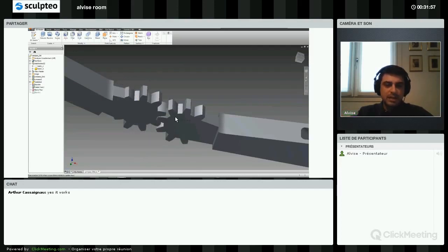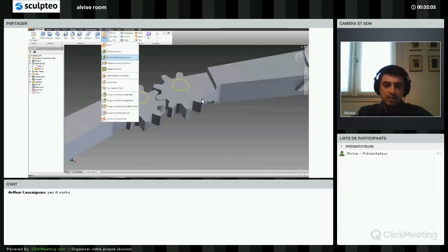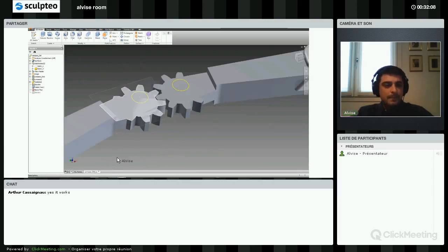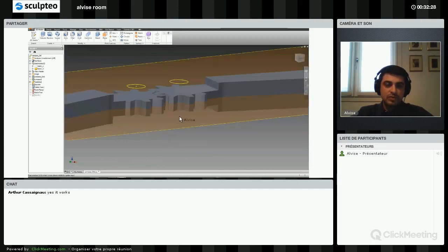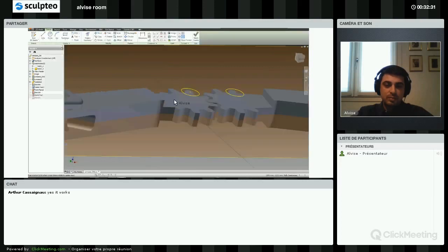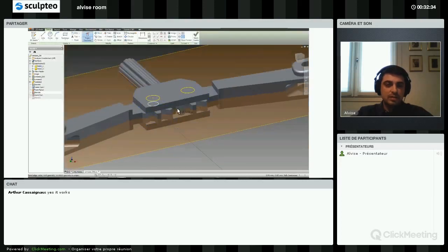I want to create a sketch on this new plane to extrude the kind of sticks to make this part move. The base sketch for this new stick I want to create will be found in the middle component. I will again project its diameter, which I haven't canceled on purpose, on this new sketch. It's done. Alright, I finished the sketch as well.